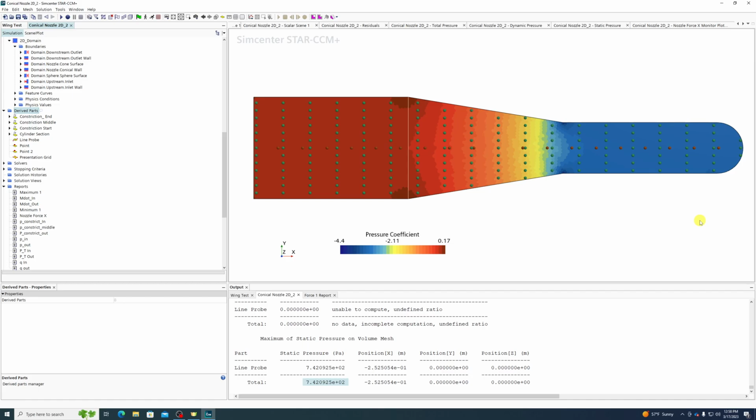It's not quite what I do right now, because I deal with satellites in space where there's no air. But one of the big things we do is model correlation. We build a thermal model for the satellite. We look at what that thermal model says about what the satellite's going to do in the test chamber. And then we build a model for what the satellite's going to do in orbit. And then when we run the test, we go back to the model and tweak all the parameters to get it to agree, so that the model of the satellite in the test chamber agrees with what we actually observed on the satellite in the test chamber. And then we take all the same parameters and apply it to simulating the satellite in orbit. So that's kind of a model correlation effort.